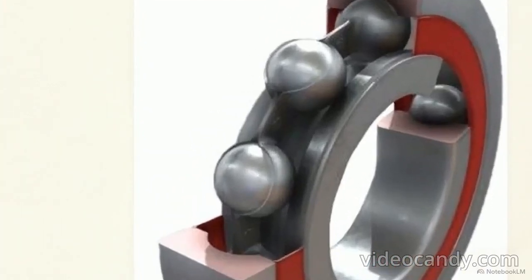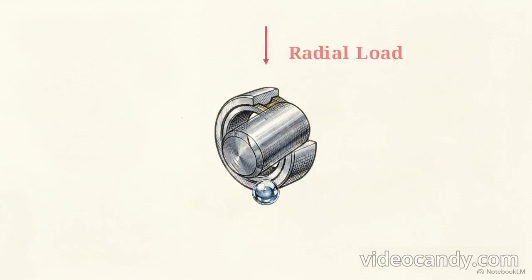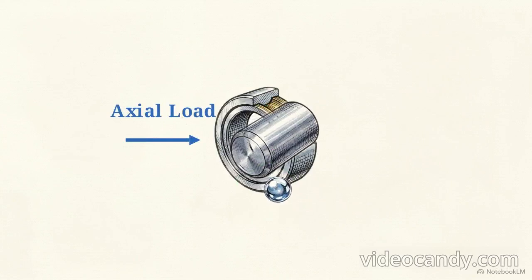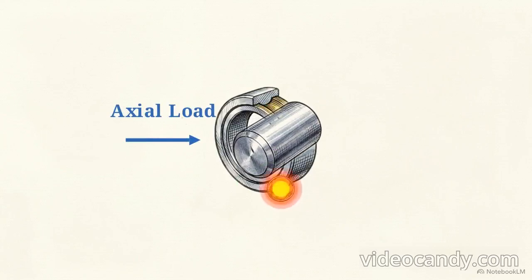Instead of relying on fluid, the inner and outer rings are separated by spherical rolling elements nested tightly within deep machined raceways. When perpendicular force is applied, deep grooves channel the stress into the spheres, smoothly distributing the load. But if a parallel axial load is introduced, the geometry fails. The balls jam against the steep sidewalls, creating friction that will shatter the bearing.